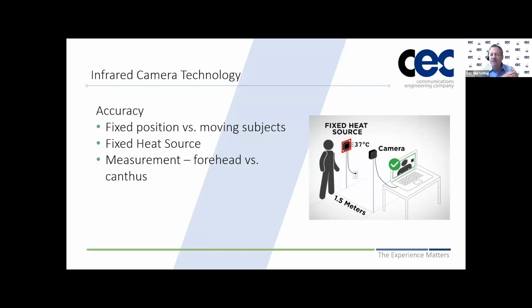It is a very precise instrument that you would put in the scene with the video, and it would produce a fixed temperature at, say, 98.6, and it allows that visual reference for the camera to compare the reading of the subject against. That really has a large effect on the accuracy of these systems. As a matter of fact, a lot of times without that, they can't achieve the accuracy that you might read in the specifications.